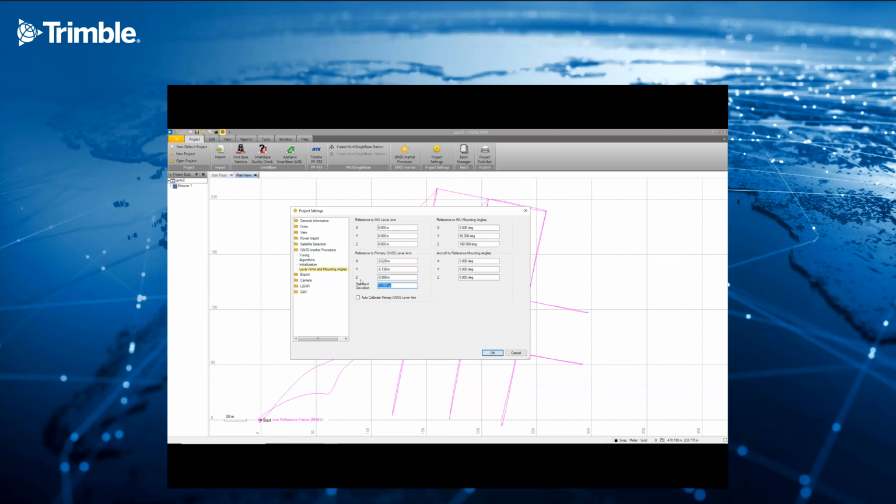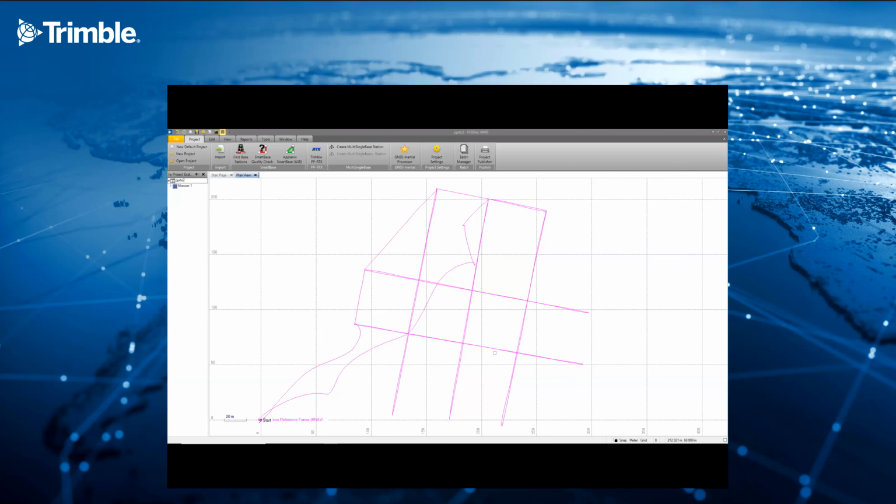And I will set the standard deviation to 0.01 meters. The IMU rotation angles are already visible here. You will get these values by measuring them, or in case you have a CAD model, this would be the best option to have precise data. I'm going to save it.